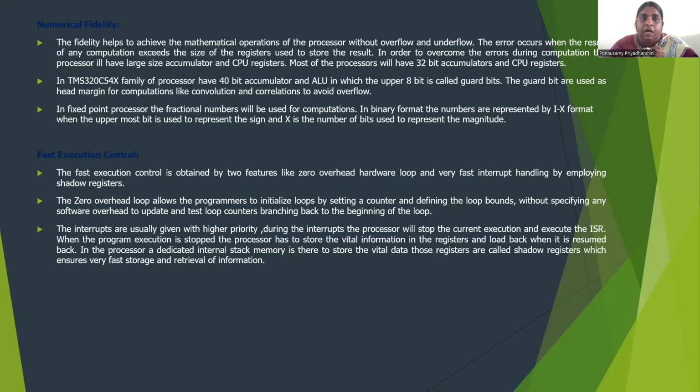Numerical fidelity helps achieve the mathematical operations of the processor without overflow and underflow. The error generally occurs when the result of a computation exceeds the size of the registers used to store the result. So to avoid those conditions, this nature of the DSP processor is very helpful.